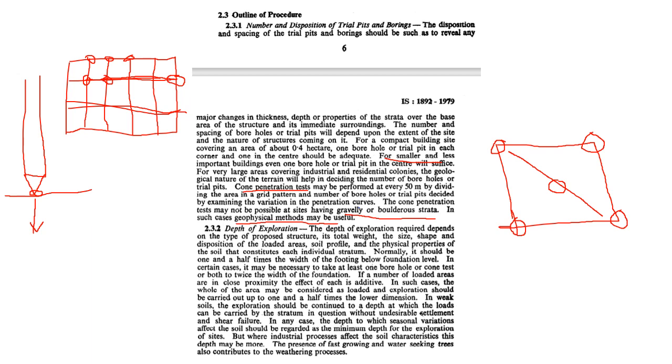So it is always ideal to take the borehole up to that hard stratum or up to that bedrock level, so you are assured, okay. And one more thing, once you reach the bedrock, don't be under the assurance that okay, your bedrock is found, now you can stop digging. No, once you find the bedrock, it is important that there is actually another clause that you should dig at least 3 meters into the bedrock,